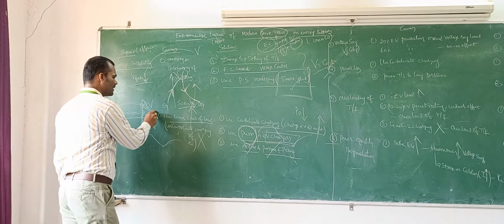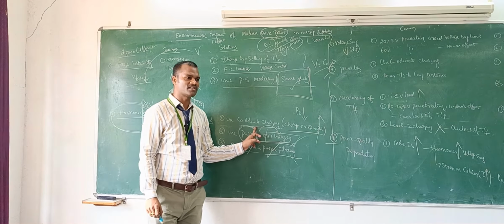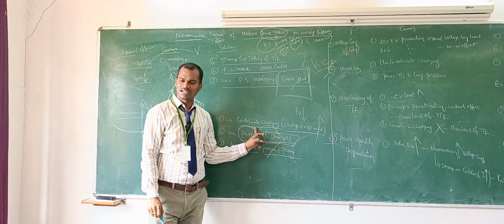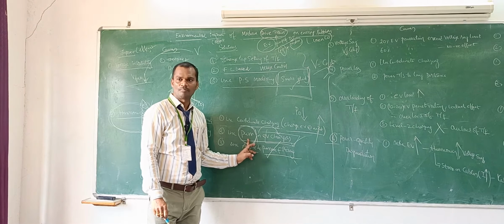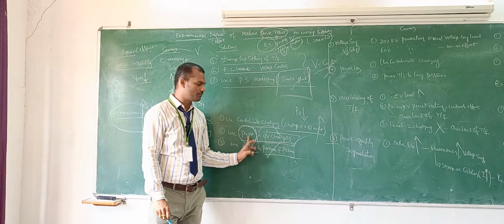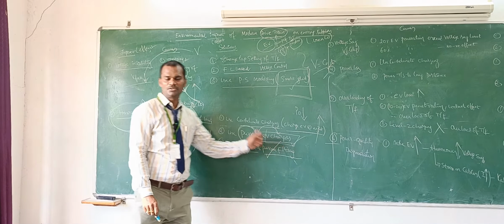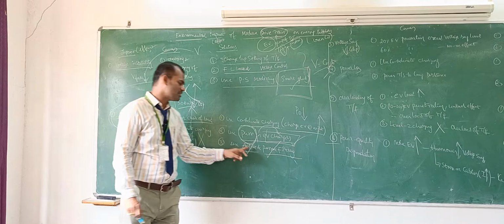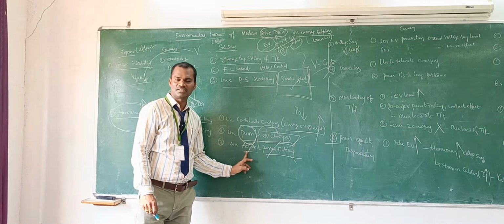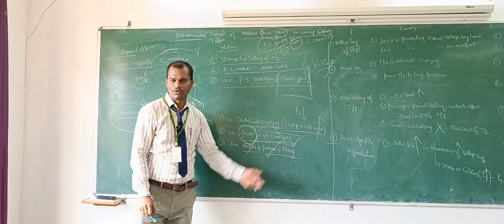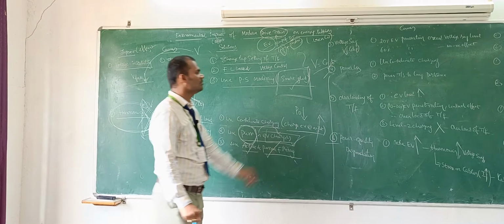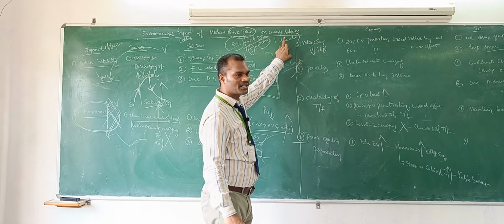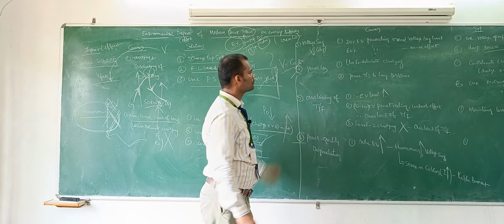So this can be mitigated by using coordinated charging. What is coordinated charging? Charge electric vehicles only at non-peak hours and use pulse width modulation technique for the EV chargers to reduce the effect of harmonics developed by the chargers. Use active filters and passive filters at load side, which can eliminate the harmonics in the power system. Therefore, the power generating companies will not struggle.